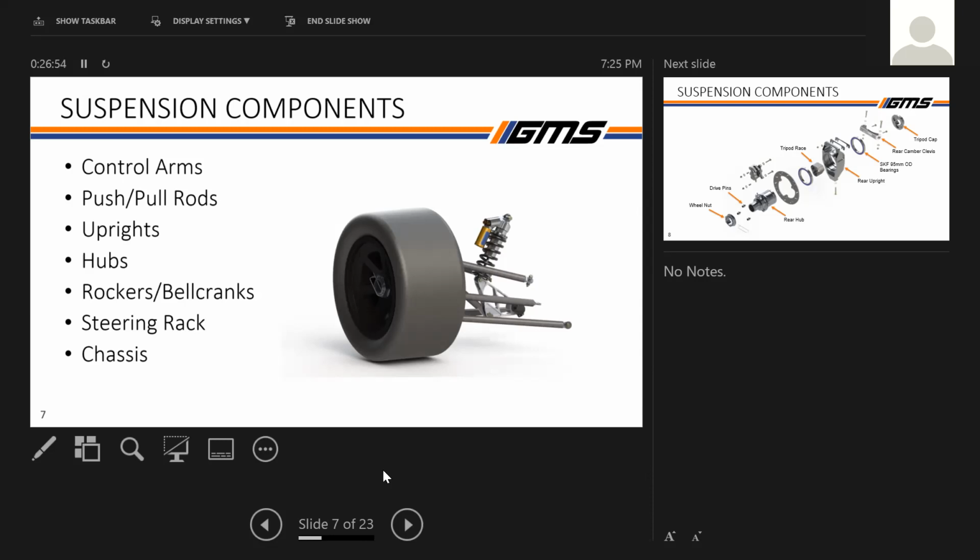This goes back to vertical load on the tires and tire grip. Tire grip is, as I showed on one of the slides, a function of your vertical load on the tire. So if we think about a wing, airplanes fly, they generate lift. We flip the wing upside down, we generate downforce. Downforce pushes down on the car, and that's more vertical load on the car, right? So then we in turn get more grip on the tires, which helps us go faster in the corners. We don't necessarily need as much in the straights, but in the corners we get more grip from the aero package.